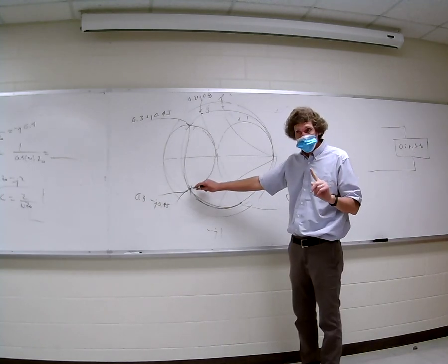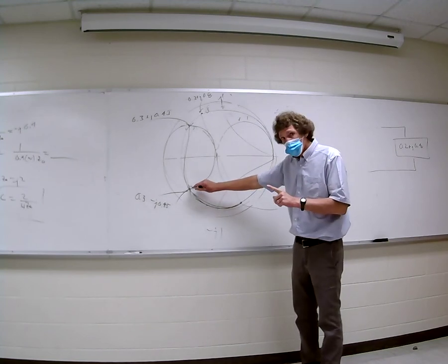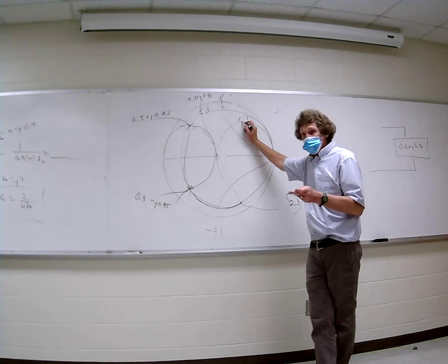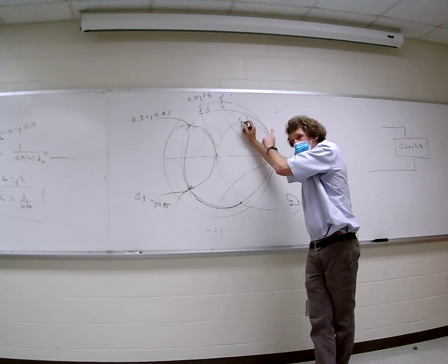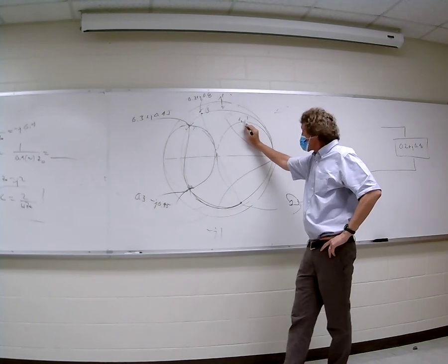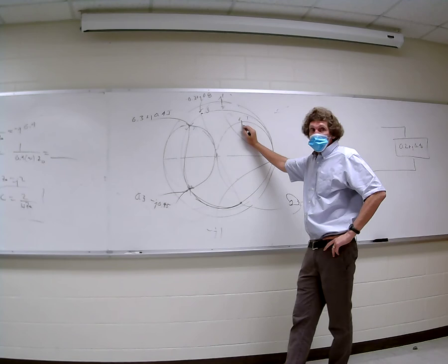Now listen carefully to this. I'd be adding a capacitor in parallel. But when I go from here, on a rotated circle, to here, now I get 1 plus j something, right? That was impedance, admittance. Now I'm back to impedance, right? If I have this and I get a plus, do you all agree this will be a plus j something? This would be impedance. Plus j means I've got to add minus j. That would be a capacitor. Do we want that? This is in series. This would be impedance. We don't want that.